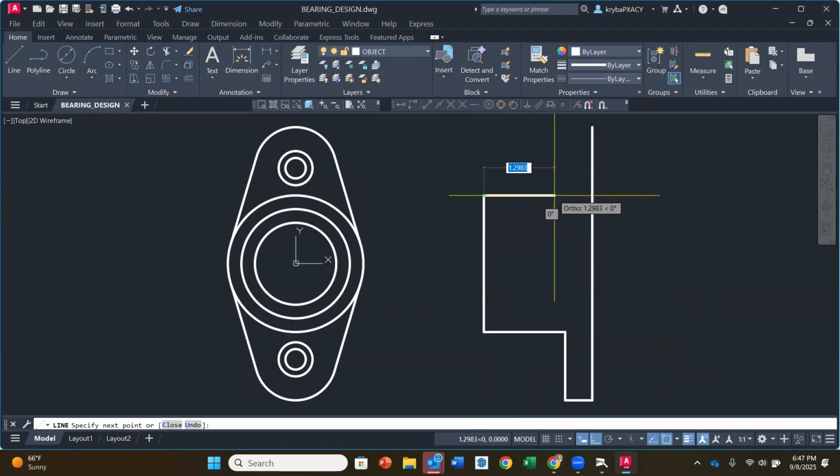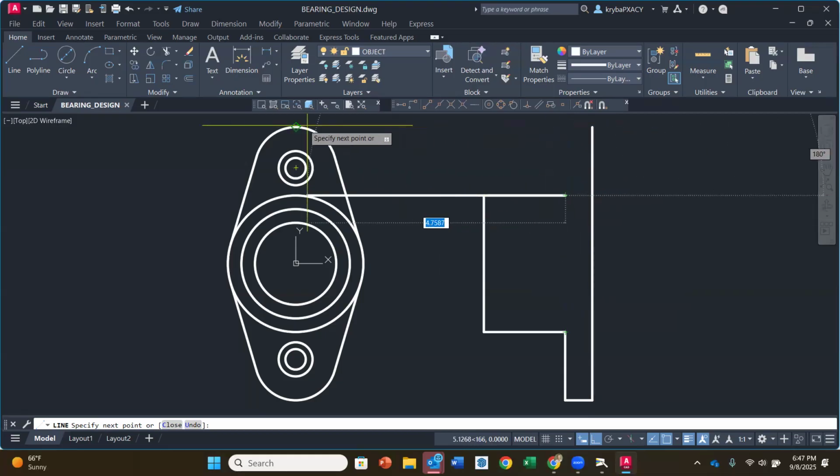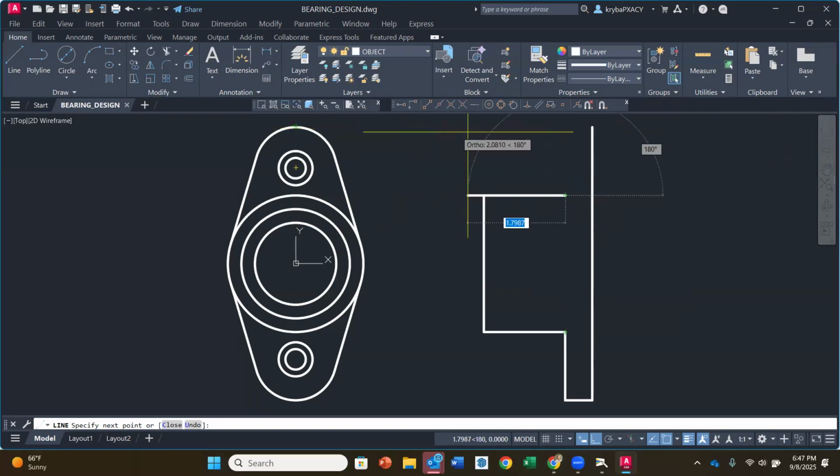We could do 1.5 here, or we could activate that corner to be in line with it as well. Okay, either way. And then we're going to go back up. You could either go back over to the top of our arc or to the end point of the line that we already have in place, and it'll snap to that. And then because this is a closed loop, you can do C, enter, and it'll close that loop. Okay, or that figure.